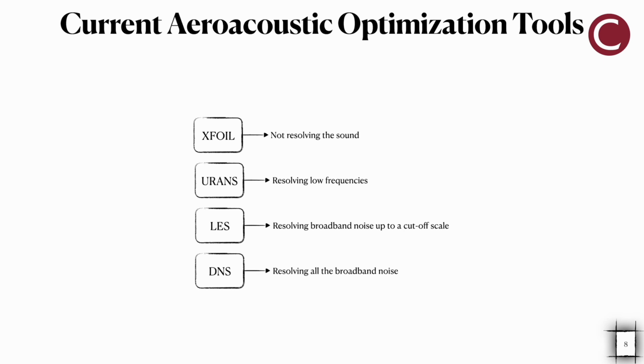But it's not very reliable for viscous flows. And whenever we have boundary layer and wake flows, like separations and post-stall analysis, it's not very accurate for these types of analysis. But it's still a powerful tool that can be used as an aerodynamic analysis for an aeroacoustic shape optimization framework. There are so many studies that used XFOIL.